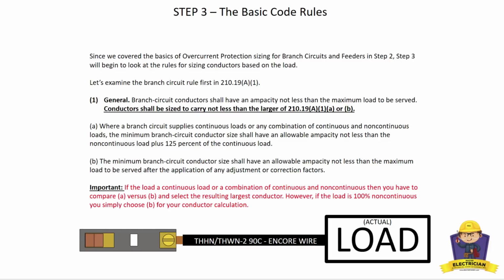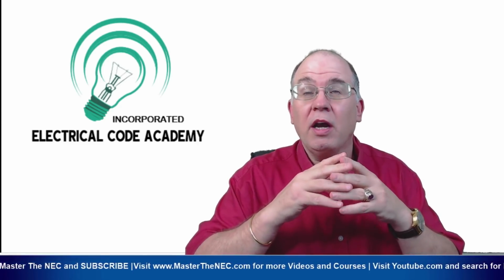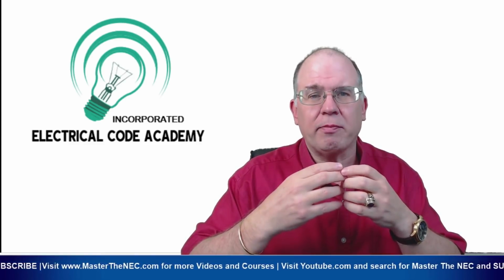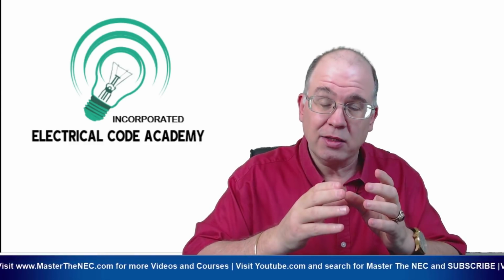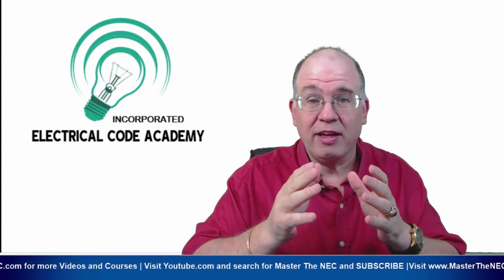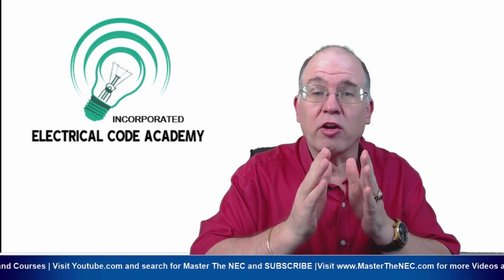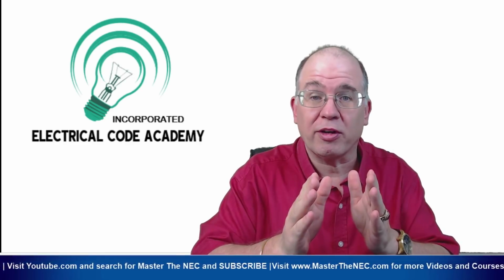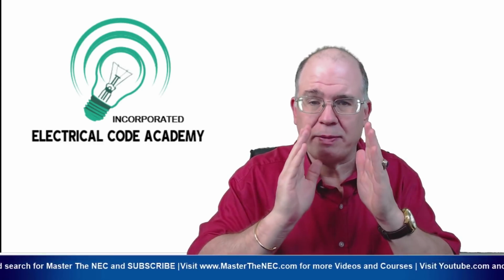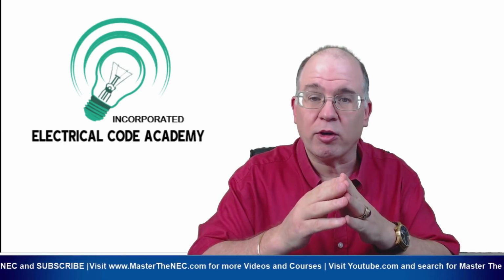Now, let's do it this way. Let's make sure I make a couple things clear. Branch circuits. If the branch circuit we're dealing with has a continuous load, then we have to do the calculation based on 210.19(A)(1)(a), which is basically going to take the continuous load at 125%, and any other non-continuous loads that might be associated at 100%. And then we're going to go to the 75-degree column, if that's what our terminals are limited at, and we just simply pick a conductor from that column. We're not applying any adjustment and corrections here. We're just simply picking a column based on the values that are in 75 C, for example, if that's what our terminals are at.